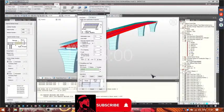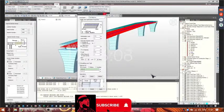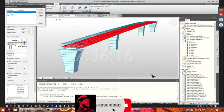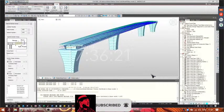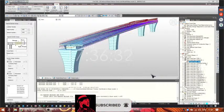We have always a carriageway of 4.5 meters. We still use the load model provided by Eurocodes, and we created all the load cases that we needed. These are the vehicles, load model 1, load model 2, and the moving load cases are characteristic, frequent, and load model 2. In this model, some loads along with traffic 1 have been applied as a surface load. As you can see, for example, for sidewalks, that is an edge surface load, and the action of the wheeling surface.